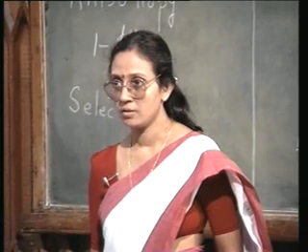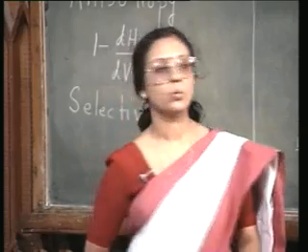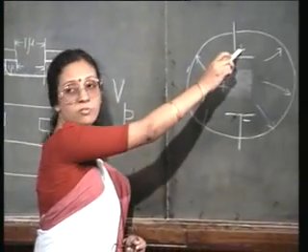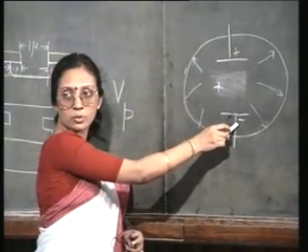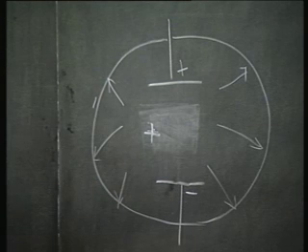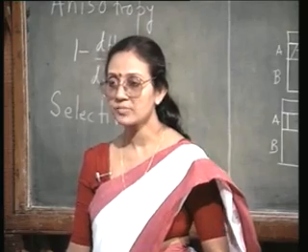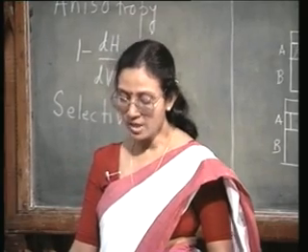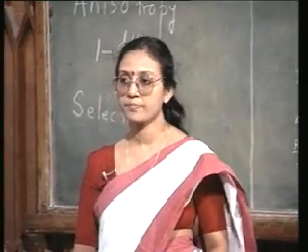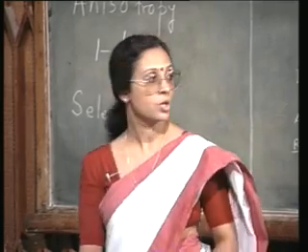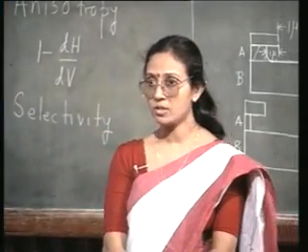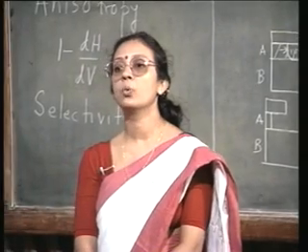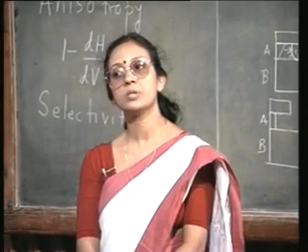That is, during one half cycle, one electrode is going to be positive, the other electrode is going to be negative, and in the next half cycle the situation is going to reverse itself. So, over a period of time, I will have the same sheath potential developed across both the capacitors, only they will be 180 degrees out of phase with each other.